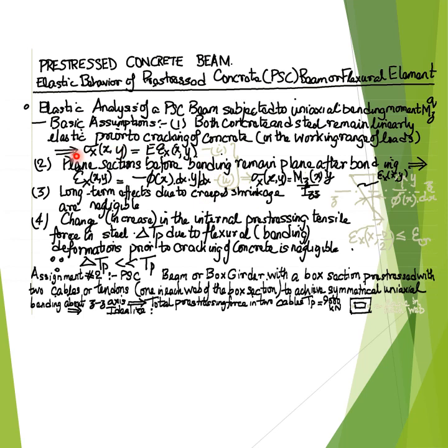Therefore, the plane sections before bending remain plane after bending in case of such slender beams if and only if the shear deformations are negligible in comparison to the flexural deformations, and therefore shear deformations can be ignored,